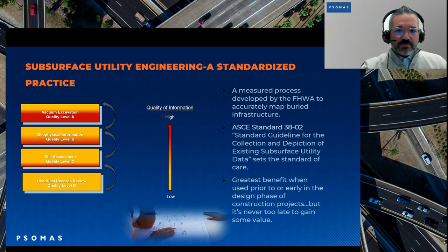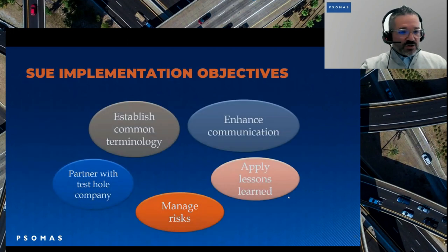So, implementation objectives of ASCE 38. We want to establish a common terminology, and it basically did do that. It enhanced communication. It started to get the surveyor to talk to the design team to talk to people in construction. It started to create this cohesive communication as the project moved through 30, 60, 90 and into construction. It also created a partner with the test hole company. Now, instead of just giving the potholer or the test holer this plan and saying, go out and punch all these holes in the ground, now you're partnering with them for a smarter plan.